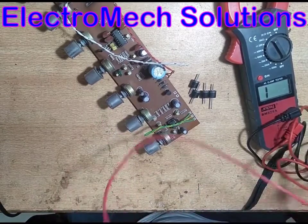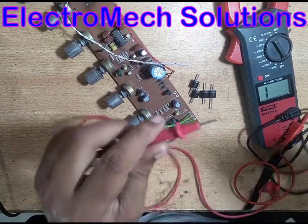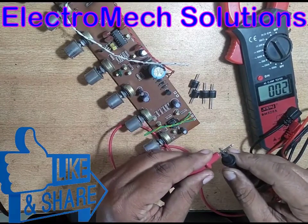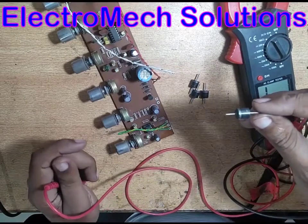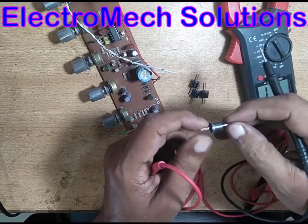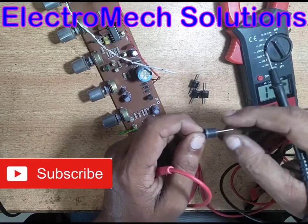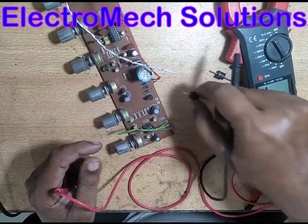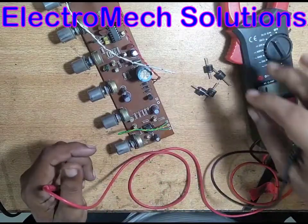As we can check the continuity of our probes, you can hear the sound. Our probes are now connected properly. This is a diode of 10 ampere. The bar side shows the negative side, that is called the cathode, and the other side is called the anode, that is positive. Every diode has the marking with the bar on the negative side and the other side positive.